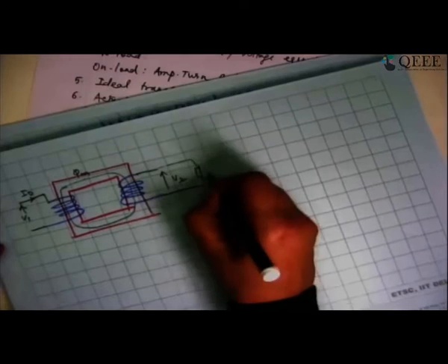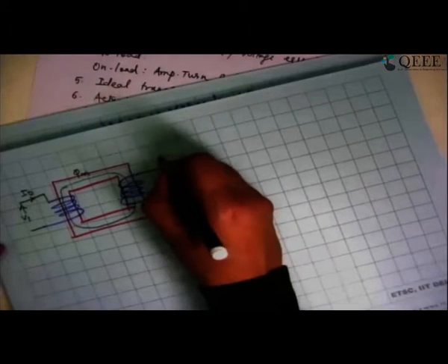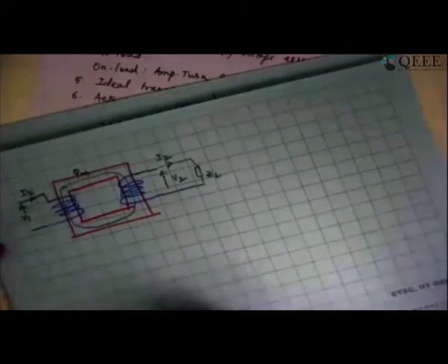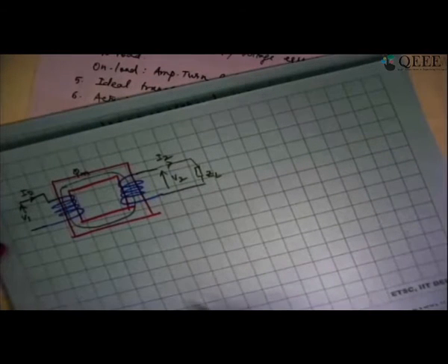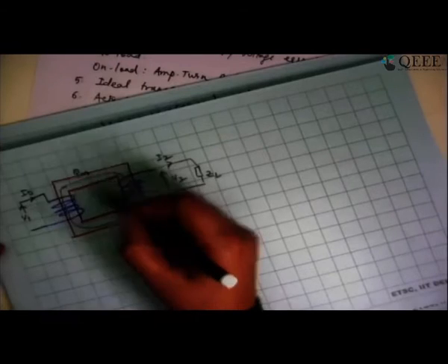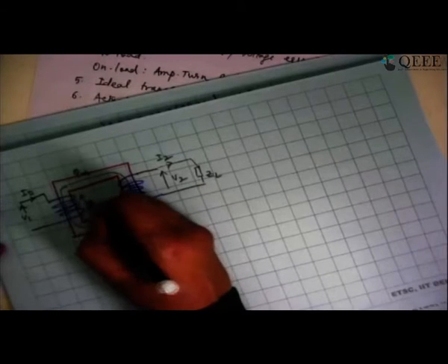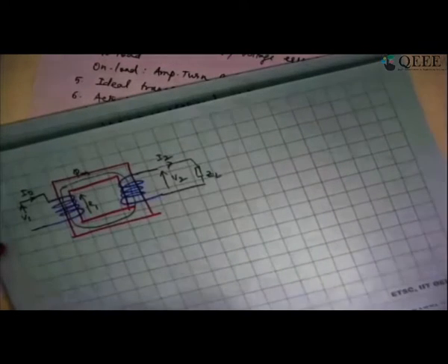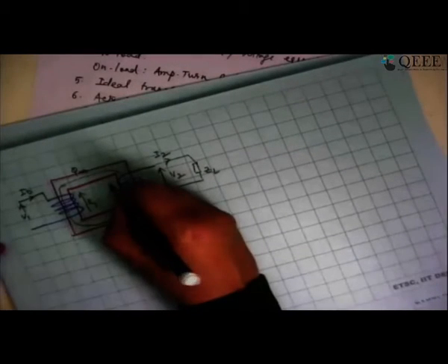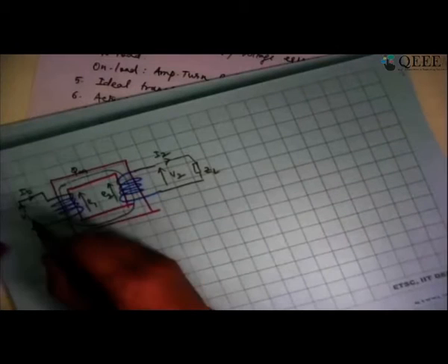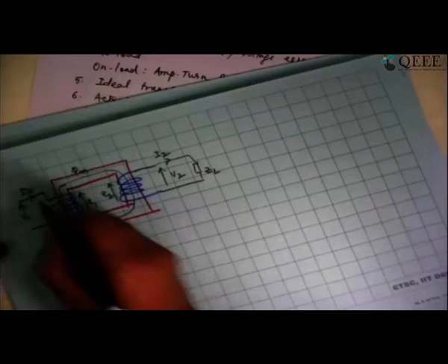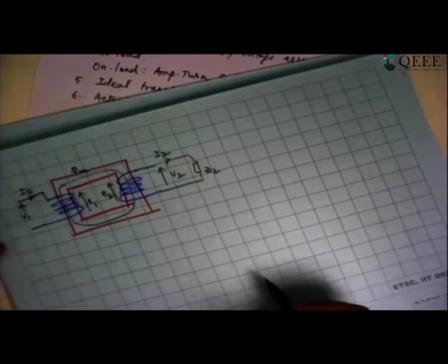load, the current flowing through the transformer, which is I2, is going to create a flux which will kill the original flux phi m. If the flux is killed, immediately the voltage which was an induced EMF in the primary, E1, will collapse. So also will E2 collapse. Now, because V1 and E1 become extremely different, a huge current will be drawn by the transformer.